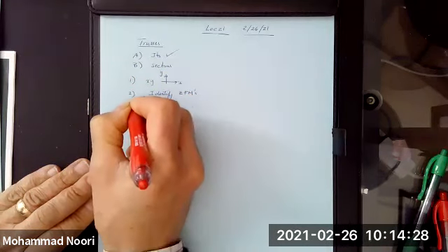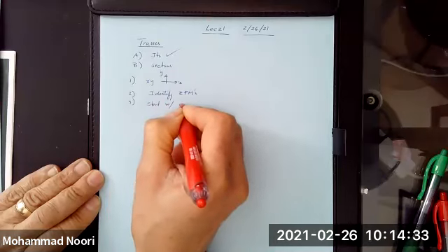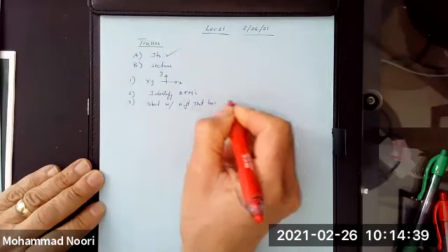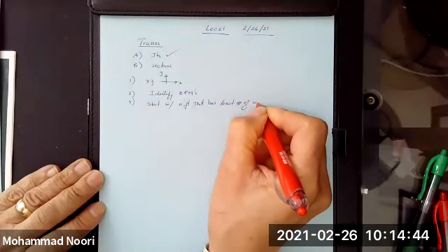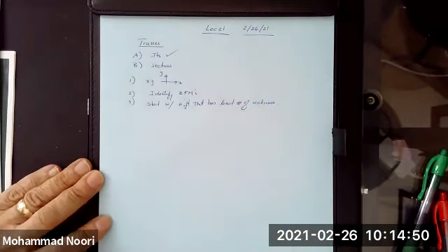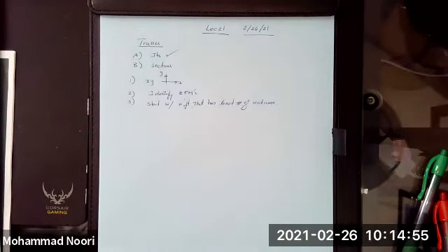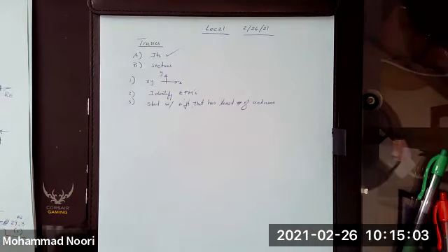And then start with a joint that has least number of unknowns. You draw the free body diagram, solve for those unknowns, move to the next joint with the minimum number of unknowns until you're done. You always end up, again, similar to frames, with one free body diagram that you haven't used. You can use that to verify your answers.